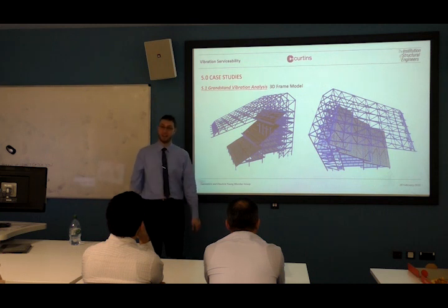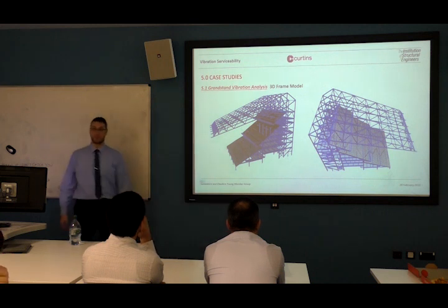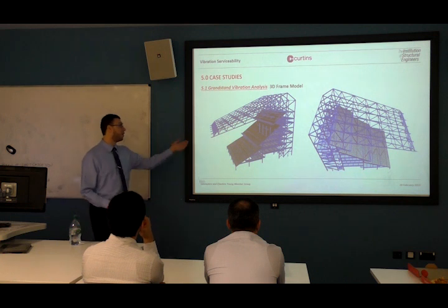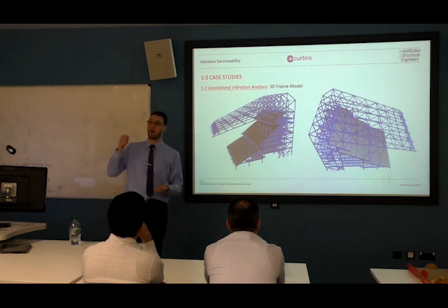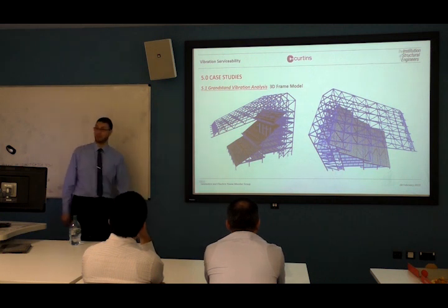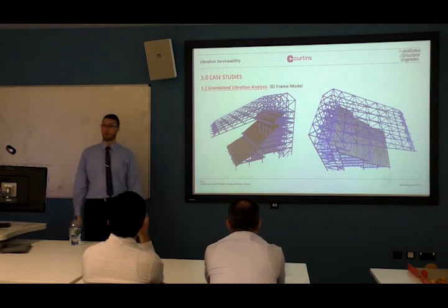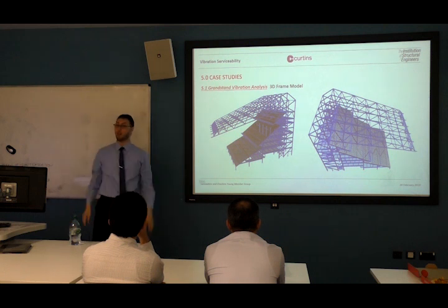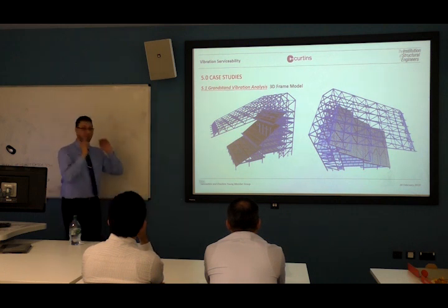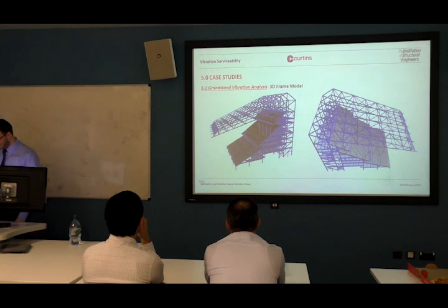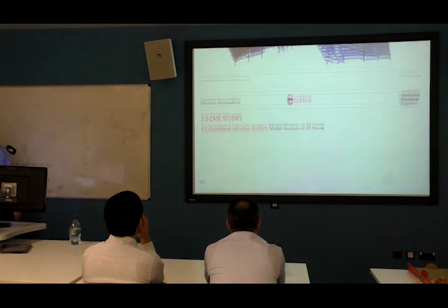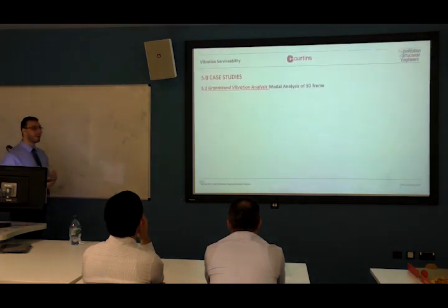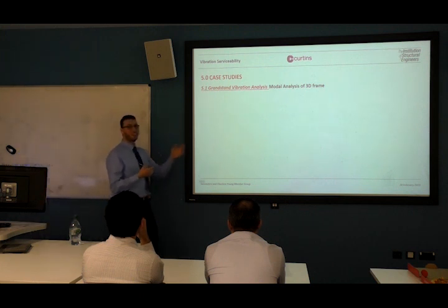Which program is that? This is ETABS. And for everyone, we apply the load on every single person as a dynamic load. And some mode shapes were the crowd doing, like, a Mexican wave. If you have a Mexican wave, you have a problem with the grandstand. But we had to check, is this correct?